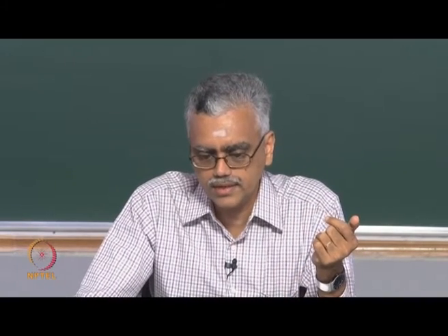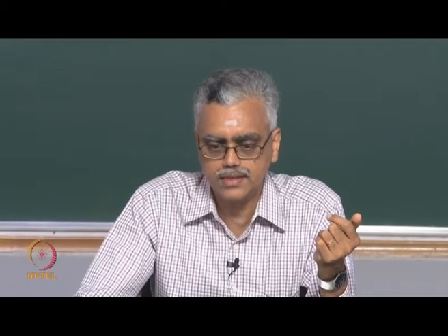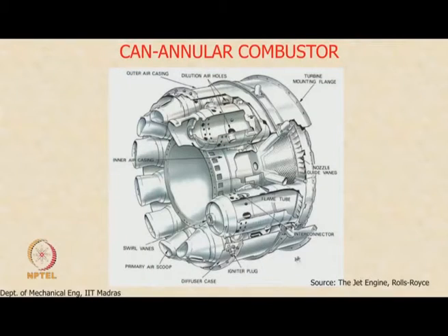All of them are interconnected, again using connecting tube, so that you can see the interconnector here. They are all connected together to maintain the same pressure in all the combustors, so that you do not have any non-uniformity in the temperature or pressure of the air that comes out of the turbine. It must be at the same pressure and temperature. Uniformity of the flow when it comes out of the combustor and goes into the turbine is very, very important.